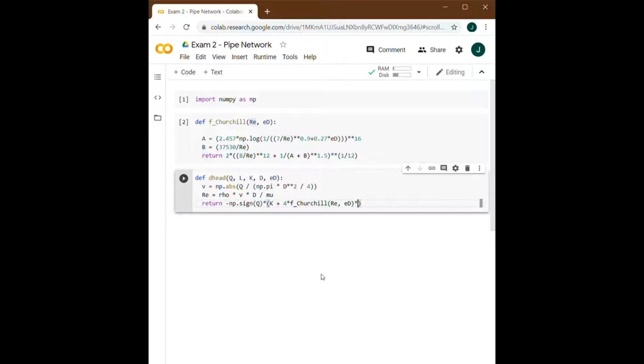Then we're going to multiply this frictional factor by the length of the pipe and divide it all by the diameter of the pipe. And then multiplying that term by our calculated velocity, so multiplying that by velocity squared, divided by 2. Almost forgot the g. So this will give us our drop in head over the length of a pipe.